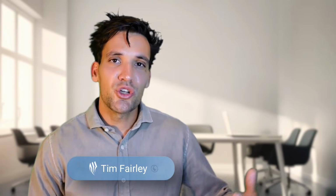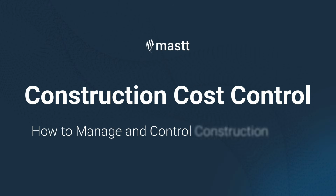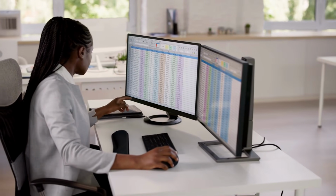In this video, I'm going to show you the exact step-by-step process you can use to manage and control costs on construction projects. I'll cover all the core costs and go through detailed worked examples so you can see exactly how to apply it in practice.